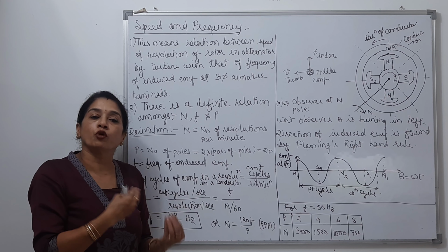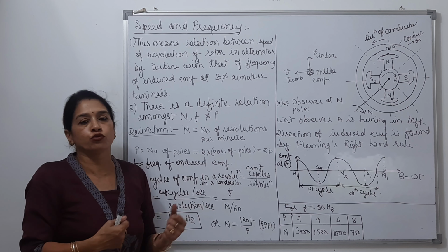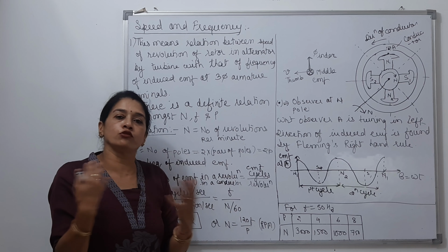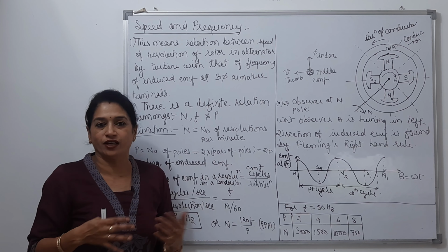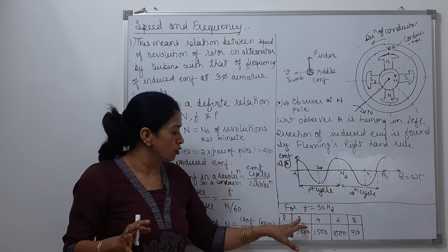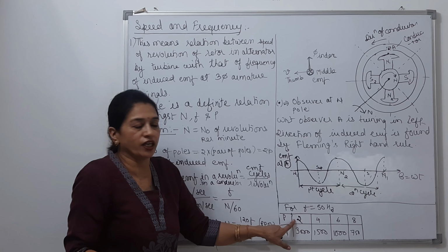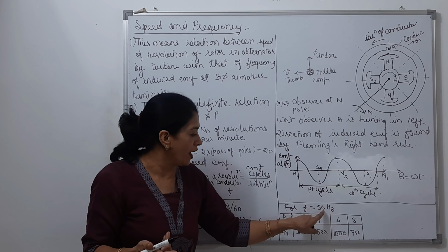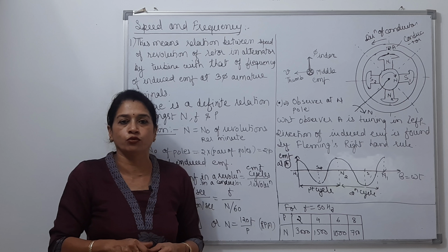We will provide a certain magnitude of speed to the rotor through the turbine. Whatever magnitude of revolution speed we want to provide, we can change as per our requirement. So we can design a two-pole alternator, four-pole, six-pole, eight-pole, and there also it is fixed that we want to generate an EMF of 50 Hertz only.